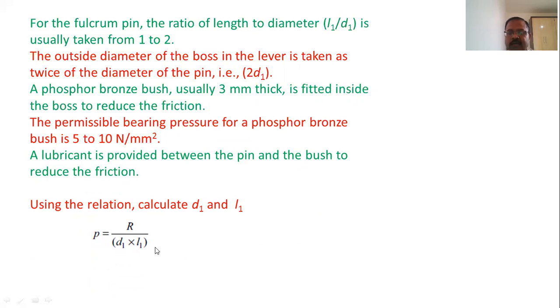See, one thing must be noted over here. If the reaction on the fulcrum pin is less than the load or effort, then we have to design those pins for the higher load, because the higher load has to be considered for calculating the diameter of the pins.